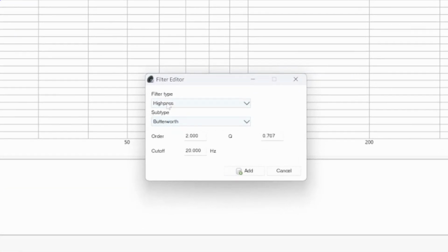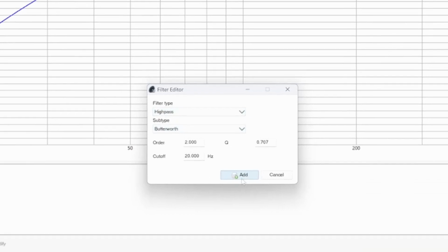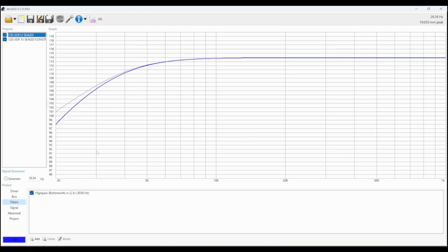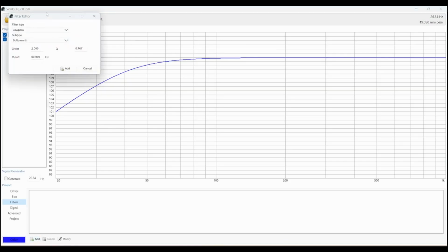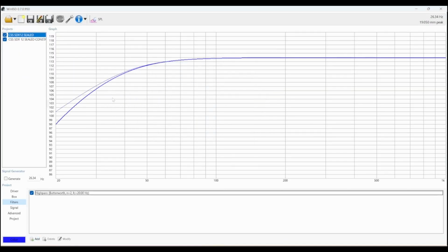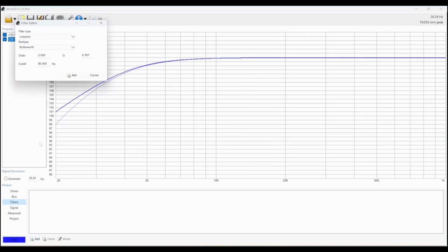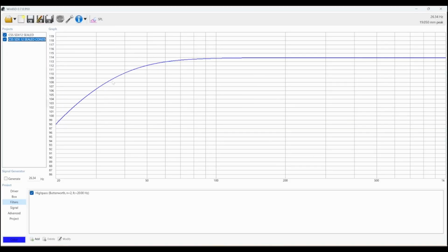The high pass will be everything that passes past this number and up is considered high pass, and this is often to match your digital signal processor. I build systems with digital signal processing in mind. Most systems will have a 20 to 20,000 hertz frequency response, and so we add this filter not only to match what the DSP can do, and I'm going to add it here to both speakers so they match up, but this drop here also affects cone excursion.